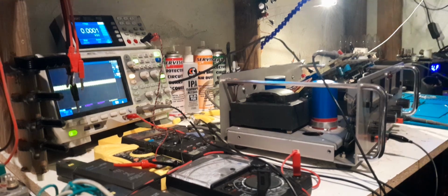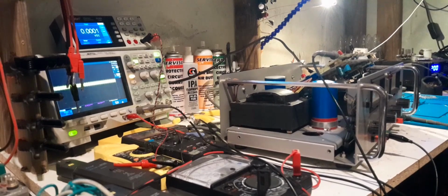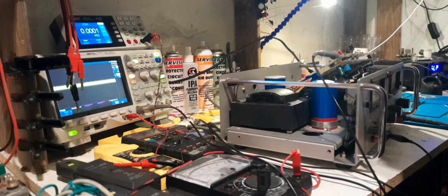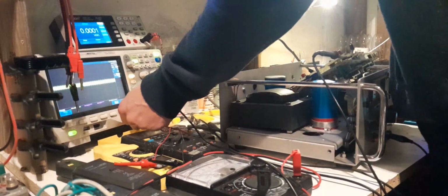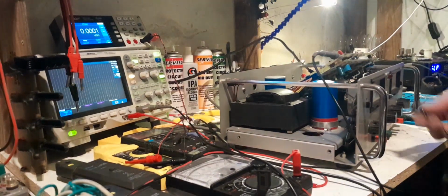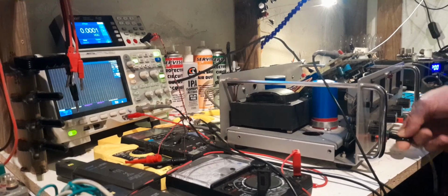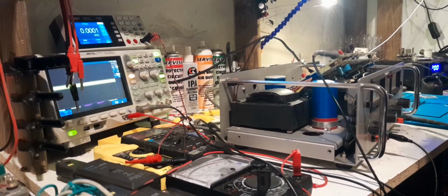So anyway, this will actually answer someone's question in the comments too, because someone asked me where my ground probe's been connected to, and that is not really something I can answer with one answer. Right now I've got a ground lead plugged in the front of my scope. I've actually got it on the negative terminal. I could also put it on the positive terminal because what I'm looking at right now is referenced to basically everything.